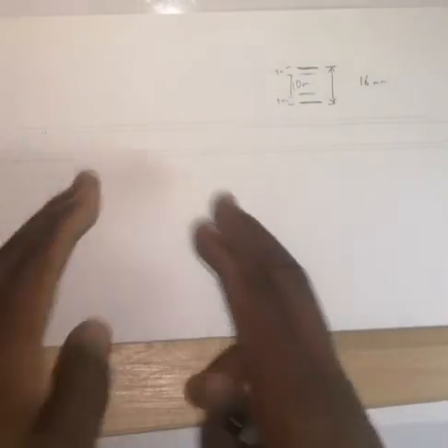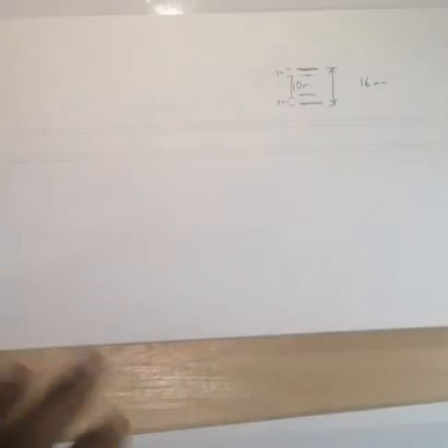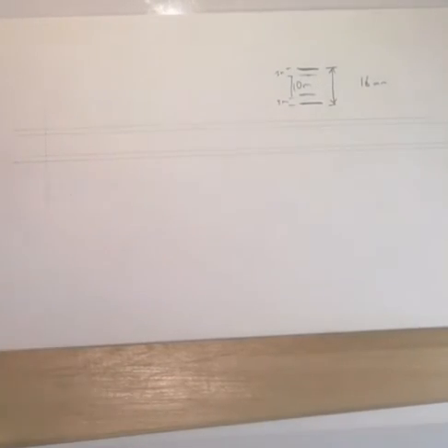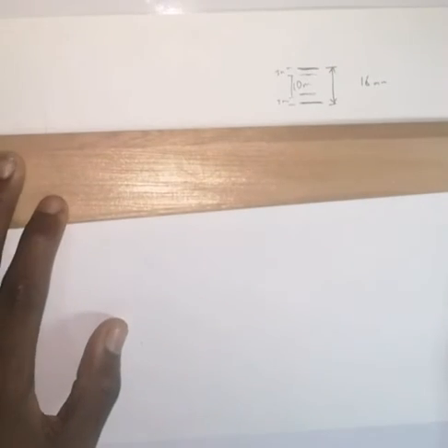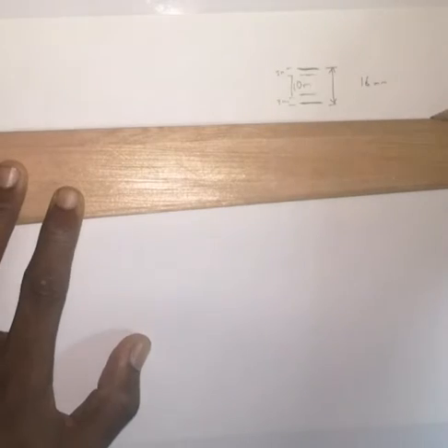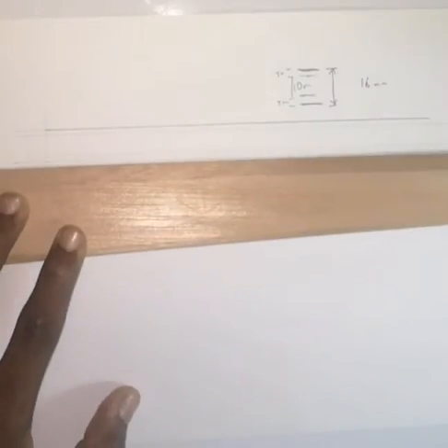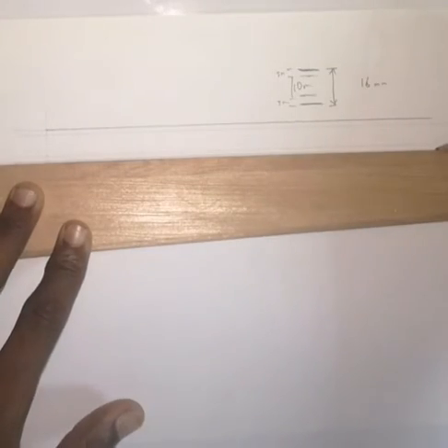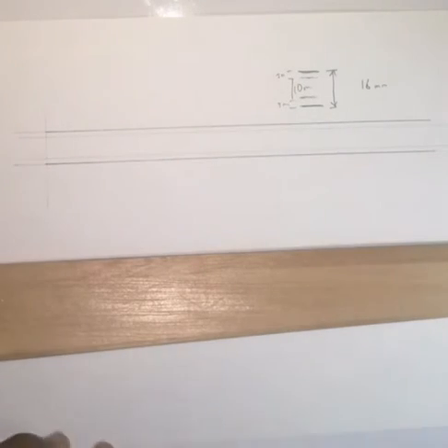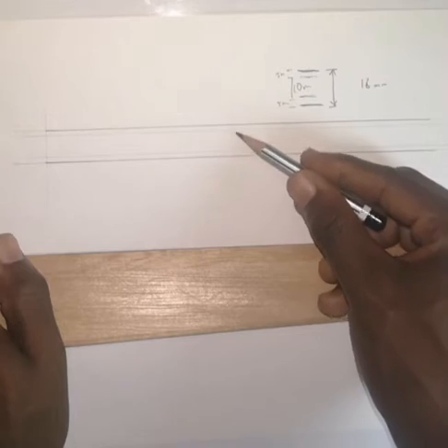Take note, I would letter to the end of my paper, and you would have to letter all the way. Your paper is bigger, you're using A2, I am using A4. Please take note. Now the lines are supposed to have varying thicknesses, as you can see. So this line would have to be thick, this would also have to be thick, and these 2 remain thin. So this is what you're expected to do. You can see clearly: thick, thin, thin, thick.